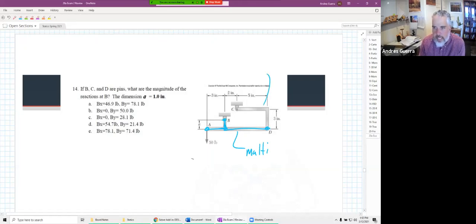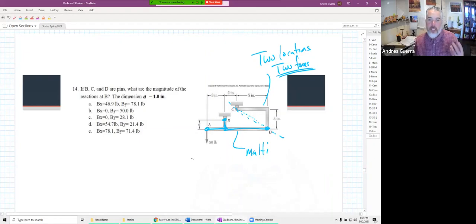C to D only has 2 locations with forces, so it's a 2-force member. When we have a 2-force member, the line of action always goes between the 2 locations where those forces occur. Our choices for FBDs is really just that multi-force member.